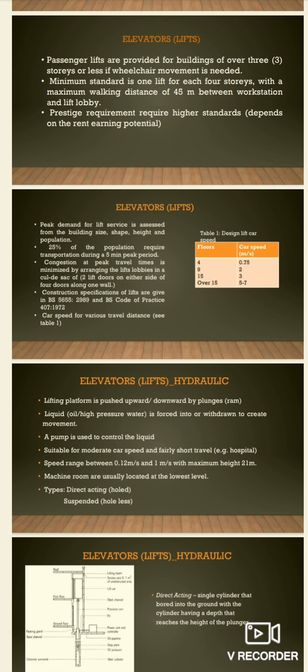Passenger lift are provided for buildings of over 3 stories or less if wheelchair movement is needed. So a hotel with more than 3 stories should provide elevators, and the minimum standard is one lift for each 4 stories with a maximum walking distance of 45 meters between workstation and lift lobby.